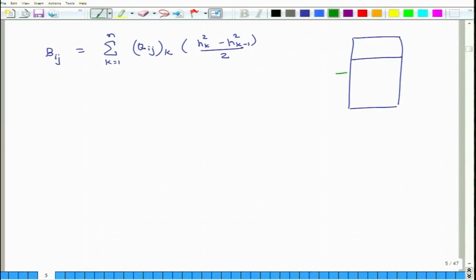this is the mid plane. So, z is equal to 0, this is H0. So, the total thickness is plus 4 to minus 4. So, here z is equal to 4 millimeters, here z is equal to minus 4 millimeters, here z is equal to minus 1 millimeters. So, in this case there are only 2 layers. This is the 45 degree layer and this is the 0 degree layer. So, there are only 2 layers involved in this.